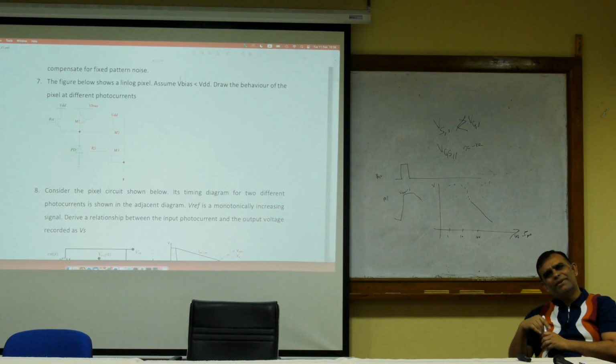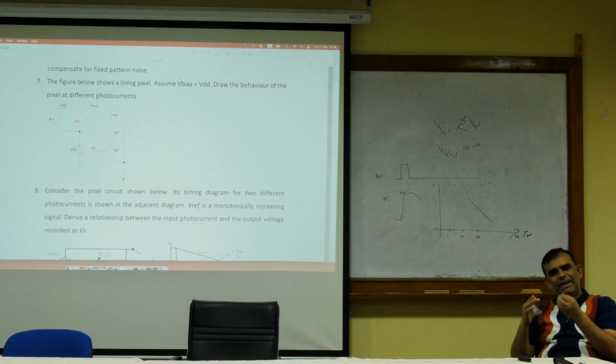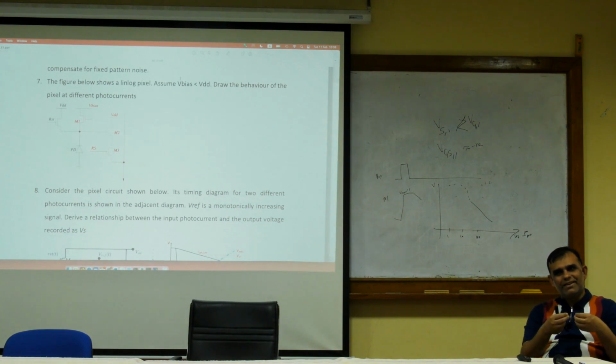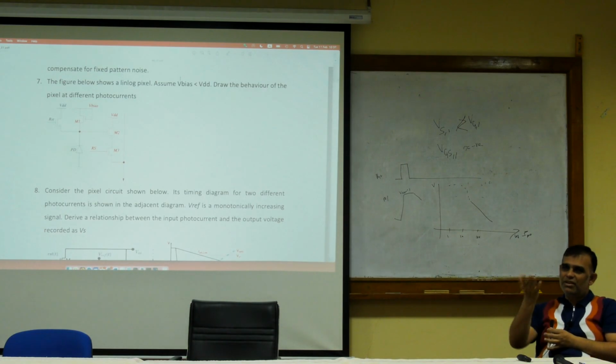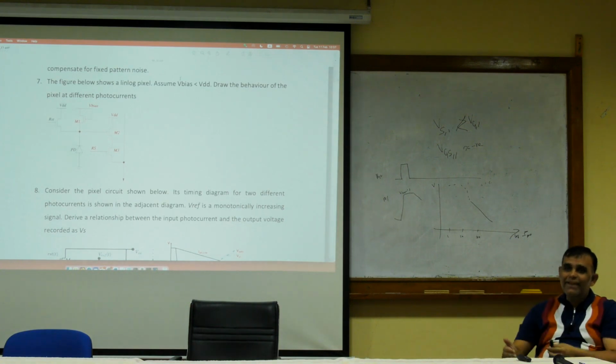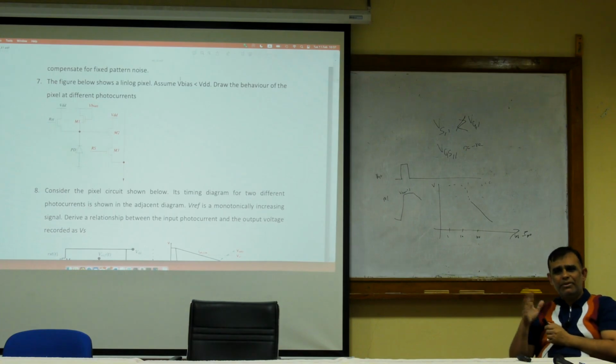How do we get color when we have got log of red, log of blue, and log of green? We get color by linearly mixing individual colors. If my individual signal is the logarithmic of that, how do we produce color? Do we do anti-log, then add and then do log again to get color? Doing anti-log, as we discussed, is a noisy operation.